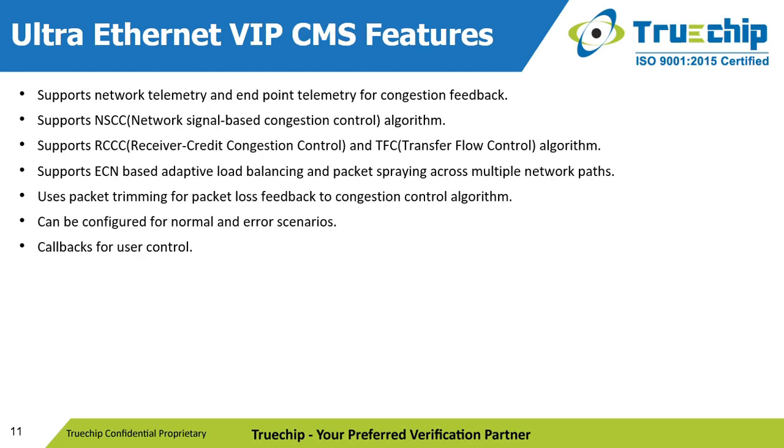For the congestion management sublayer, our VIP provides comprehensive verification capabilities. It supports both network and endpoint telemetry for congestion feedback. We have implemented key algorithms like network signal-based congestion control, receiver credit congestion control, and transfer flow control.